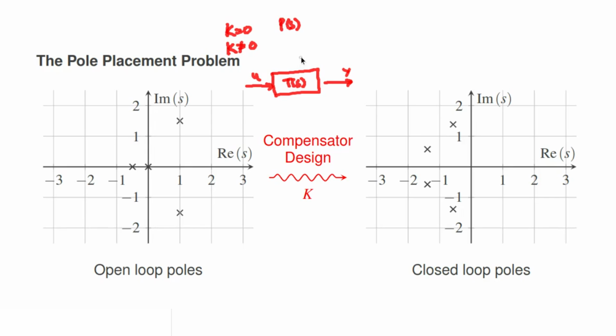We can get quite a lot of insight into how Y will respond to various inputs U by considering the poles of the transfer function in question. Roughly speaking, the output Y is given by a sum of contributions where we have contributions from each of the individual poles, and the location of these poles determines roughly how that contribution will look. Now, this is typically visualized by plotting the locations of the poles on the complex plane, as shown in both the figures on this slide.